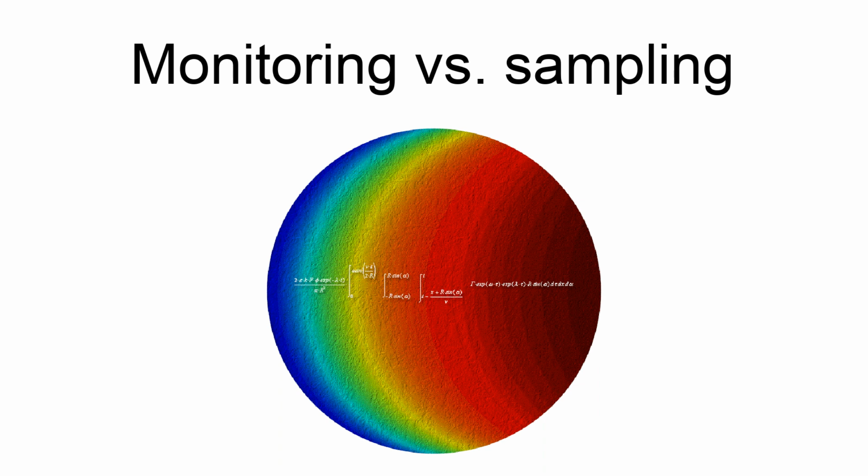In monitoring, the region of deposition of this material onto the filter medium is continuously viewed by a radiation detector, concurrent with the collection. This is as opposed to a sampling system, in which the airborne material is collected by pumping air, usually at a much higher volumetric flow rate than a CPAM, through a collection medium for some period of time, but there is no continuous radiation detection. The filter medium is removed periodically from the sampler and taken to a separate radiation detection system for analysis.